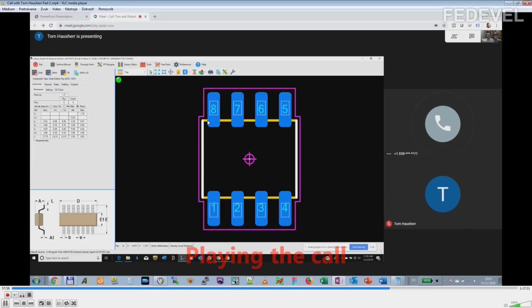Okay. Now, the package is only a 0.03 millimeter standoff, okay? That means that when you place the part on the solder paste and you go to the reflow oven, the part's going to settle down into the paste, and possibly the plastic bottom of the part is going to touch that pad, okay? And you're going to get solder all over the bottom of the part, okay? And so let's trim the pads from going underneath the part.